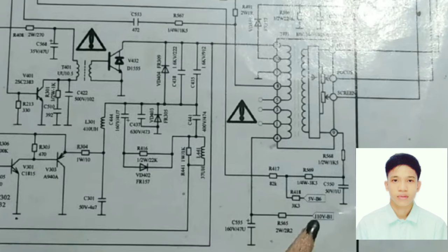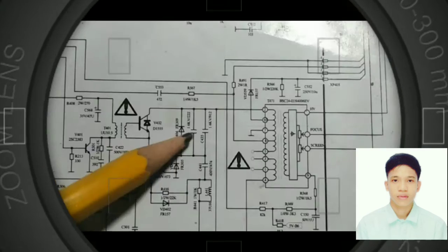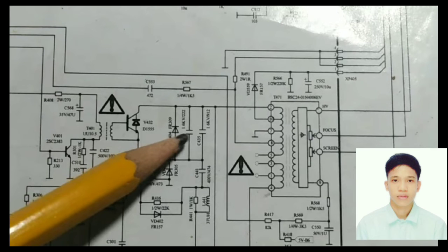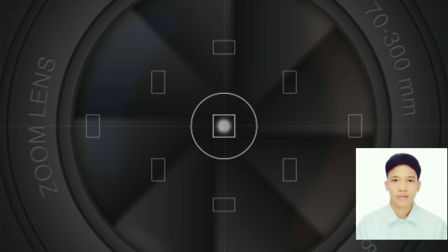To control the rise of voltage, check the B+, because if the B+ is high, it is possible the output is high. But if the B+ is normal, that means there is another issue, like a change in value of the snubber capacitor that will cause the 180 volts to rise. So we need to normalize the 180 volts to prevent some issues.